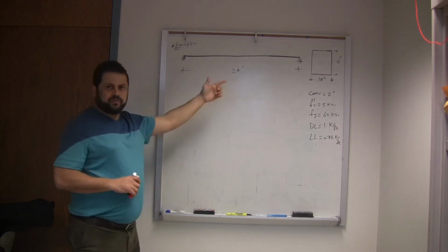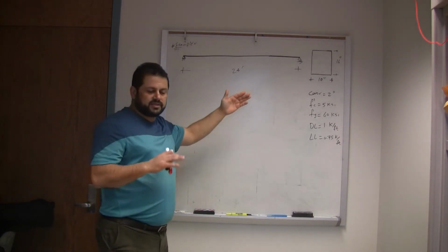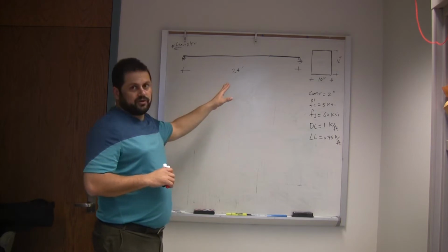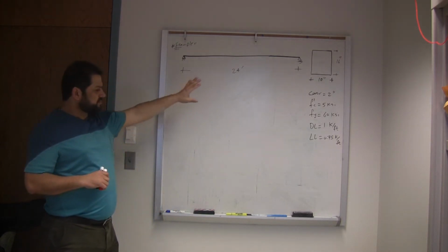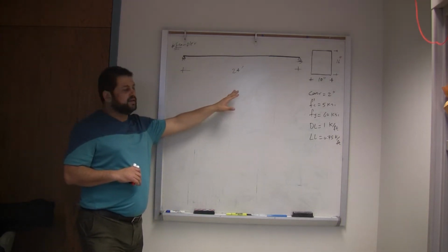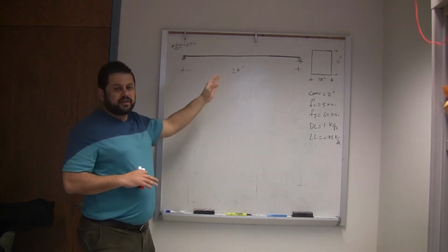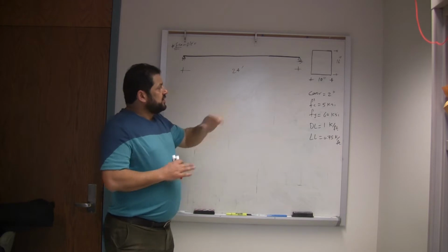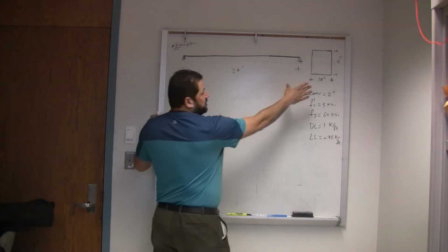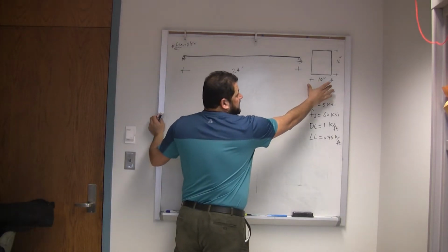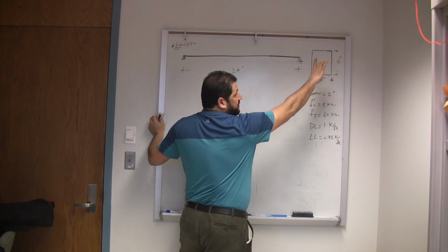Then the most important thing about this example, I just wanna show you how we calculate the deflection, or how we check the deflection and the crack control criteria. And if I have some time, I may also touch base on the development length and cutoff points. So a rectangular cross section is given to you, which is 10 inch by 16 inch.